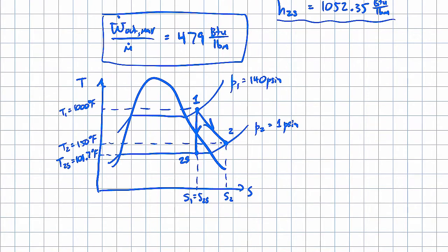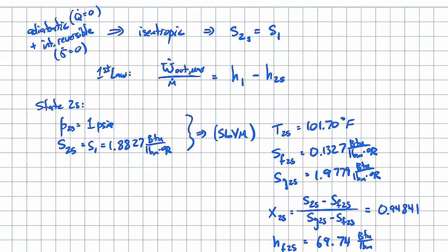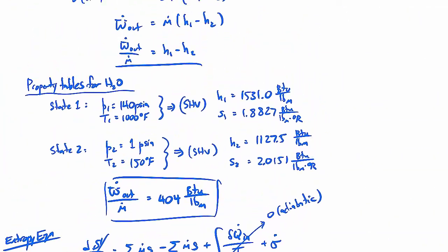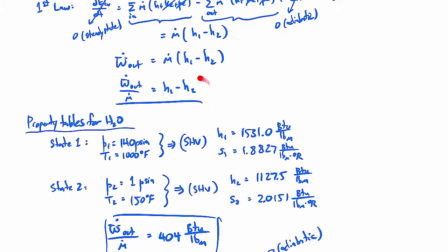Now the reason the temperature is a little bit lower for our isentropic case is because the enthalpy that comes into the flow is more efficiently converted into power. If you go back up to our first law expression, the enthalpy is sometimes called the flow energy. It's the amount of energy contained in the flowing stream in terms of pressure and temperature, like internal energy and the pressure work. That's our specific enthalpy. So the incoming flow has a certain amount of flow energy to it.